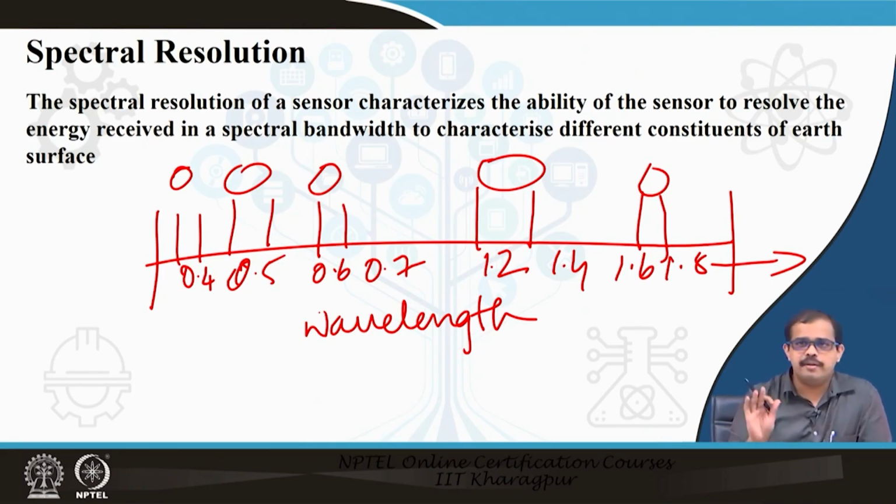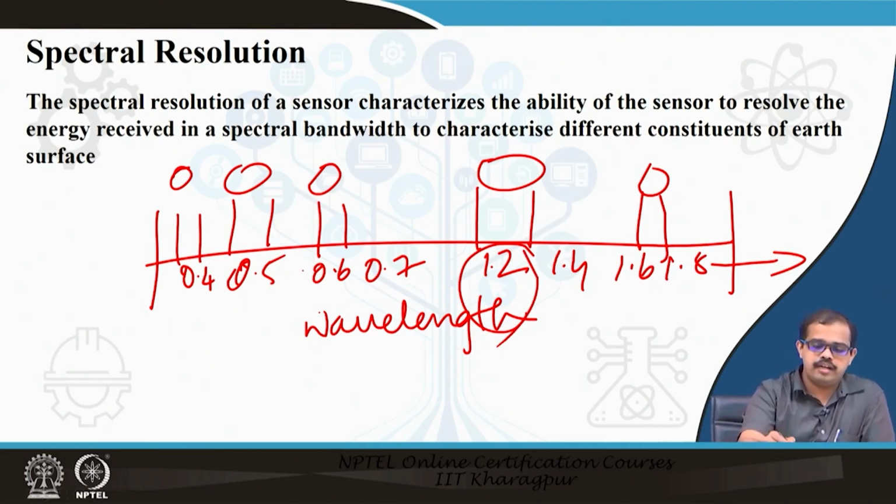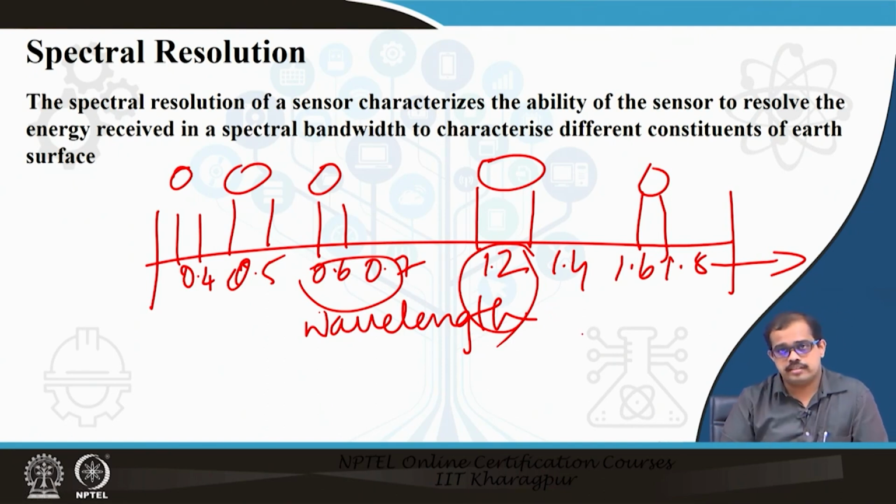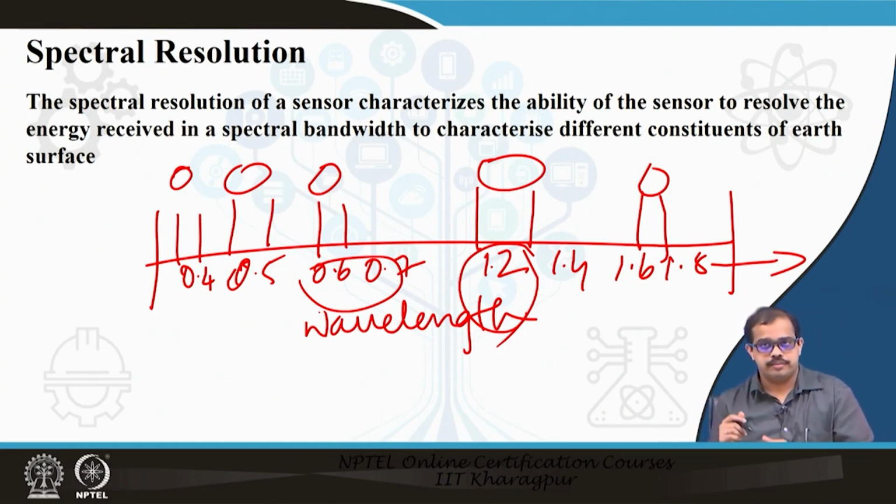It is extremely important in terms of what kind of resolution you need. For example, if you are trying to understand vegetation, you have very high reflection in the near infrared band and low reflection in the red band. So, you will obviously consider a satellite which has all of these bands. If you are using it for a variety of applications, you would look at those applications and at how many bands you need.